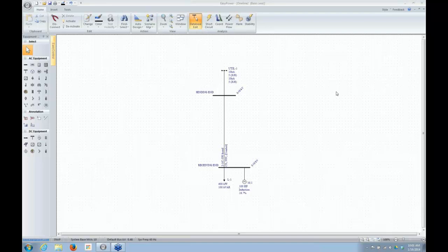If you've done a lot of design work like I have, you're familiar with the situation where you size your electrical system per the NEC and come up with the need for, let's say, a 1200 amp switchboard, and you tell the local utility you need a 1000 kVA transformer based on your NEC load calcs, and they say, that's great, here's your 500 kVA transformer, because they know that the NEC load calcs are very conservative, and typically the actual loads are never going to reach the level that you calculate by the time you take into account all the various demand factors that you add in code, 125% of continuous loads and that sort of thing.